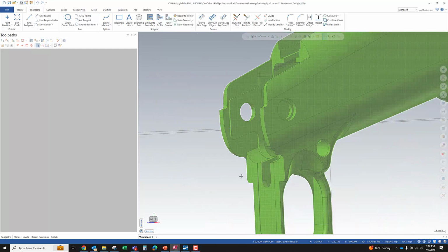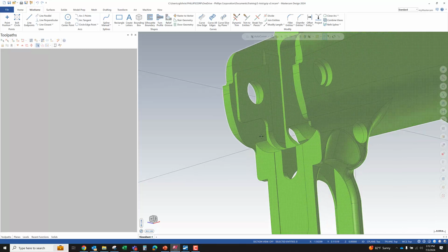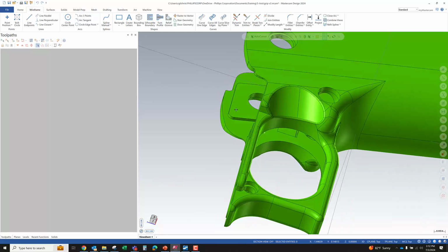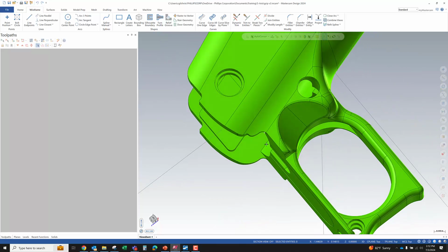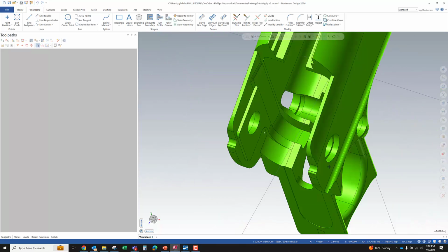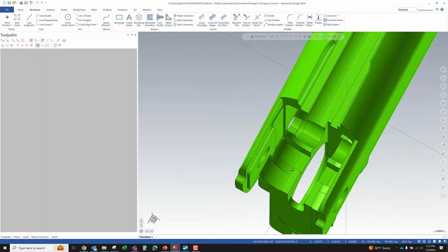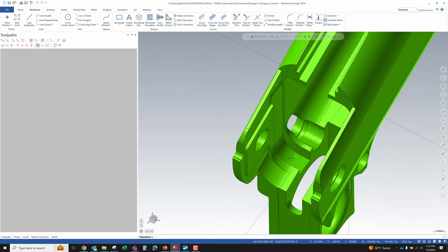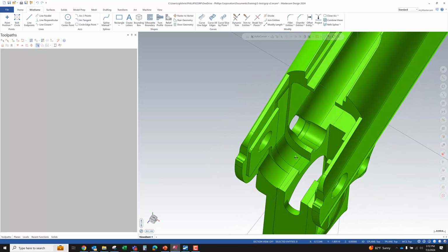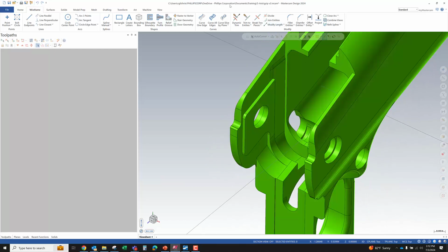That one I would approach with a slot cutter with the construction plane above where your cursor is. But if you'll just walk your cursor up about an inch in Y, there's a radius driven around a rectangular boss. No, not necessarily. On the opposite side. Here.